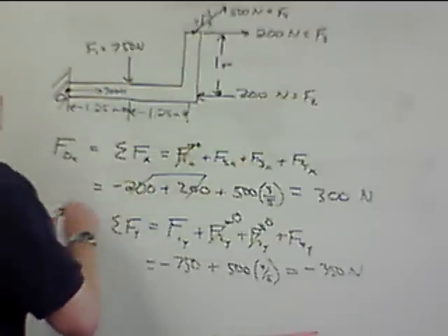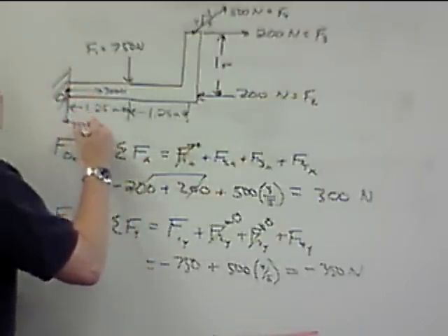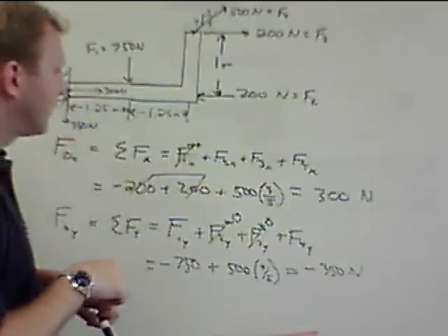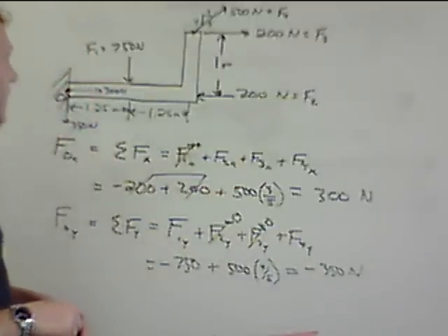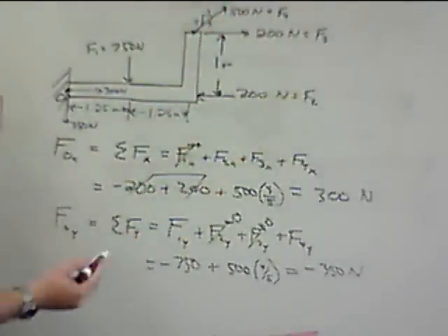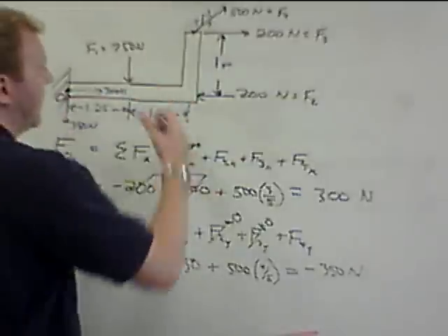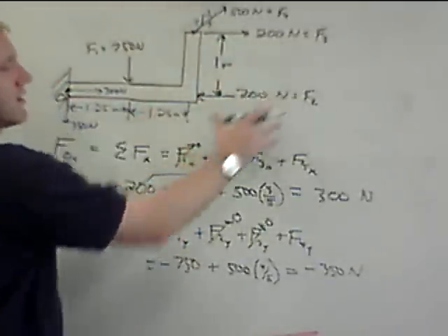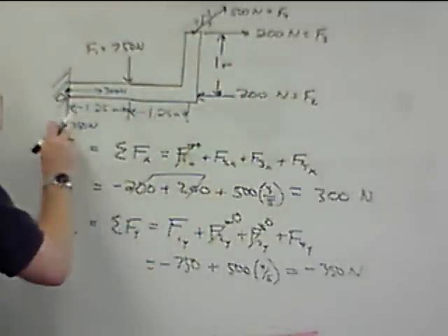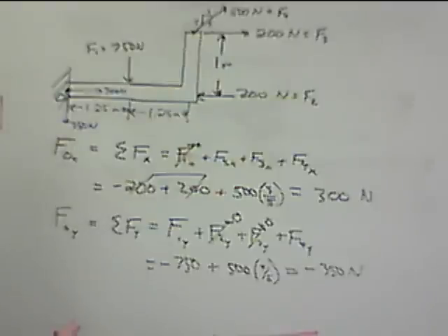So that we can draw in here as downward newtons. So what this has essentially done is taken these four forces and said, in terms of the net force moving it side to side and up and down, we can replace this entire system of forces with just one 350 Newton force down and one 300 Newton force to the right.